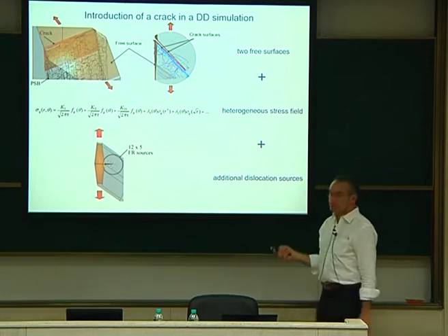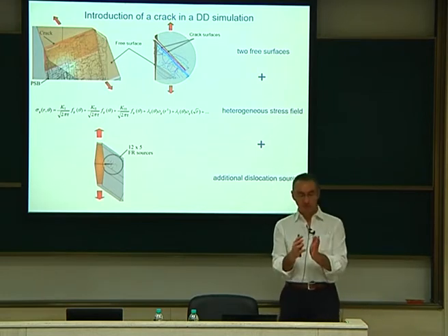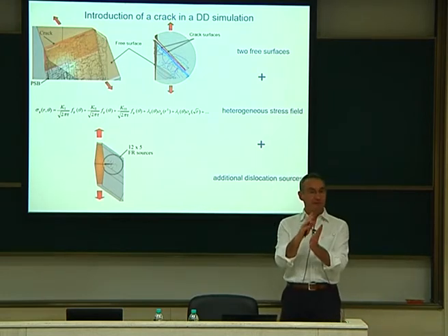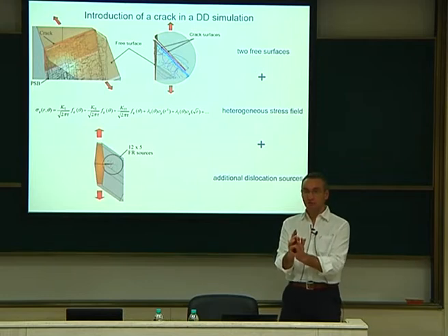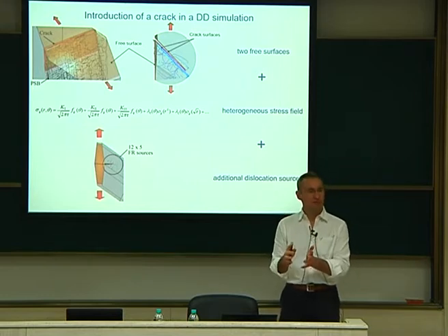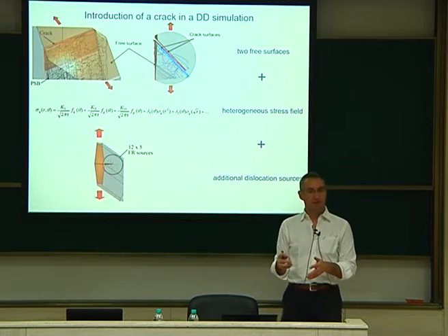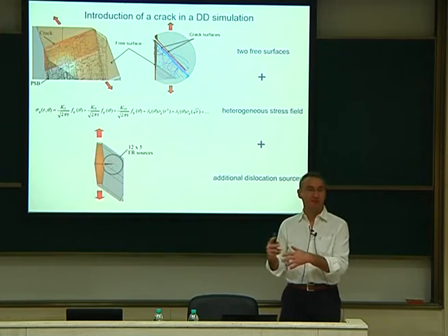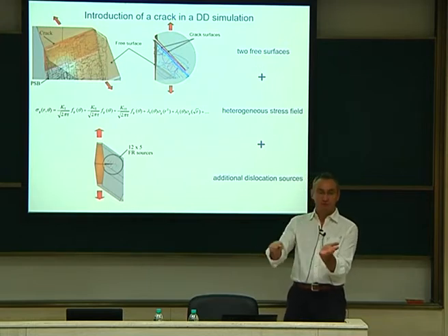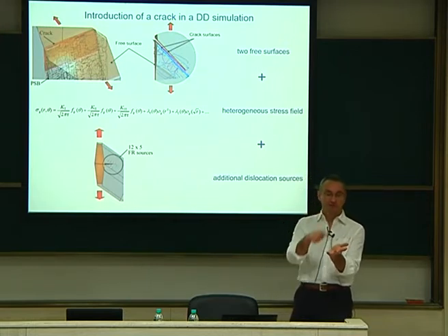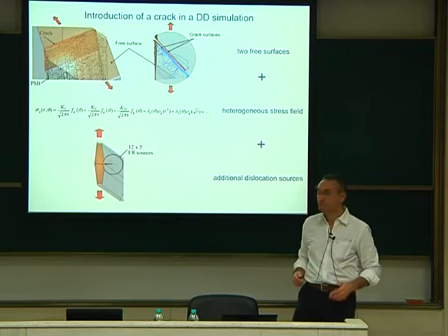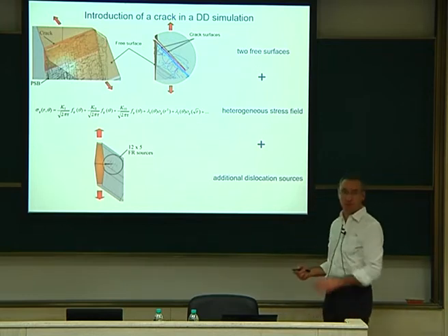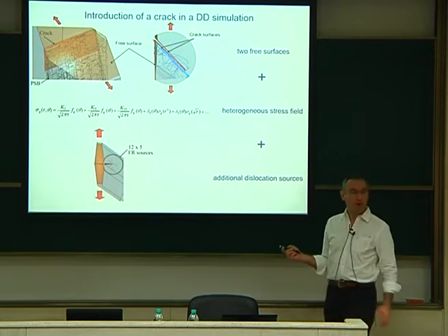Now the crack, the best way to do that would be to mesh that in FEM, typically to have the FEM modeling, FEM mesh of the crack. The even better way would be to use XFEM. I don't know if you know XFEM, so the generalized finite element method, where you can accommodate divergent fields ahead of the tip. That would be the best. Here we didn't do that. We wanted to have the first order approach.